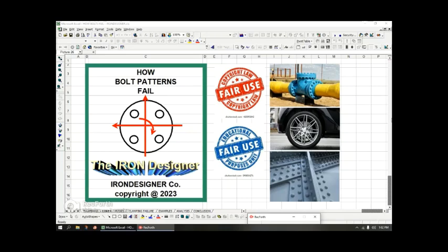There could also be a moment applied to the bolt. There's axial clamp load applied to the bolt, shear loads, torsional loads, etc. So any of these combinations and maybe more are all the forces being applied to the bolt, which is typically in tension, and that's its main mode of effect and service while it is being implemented.